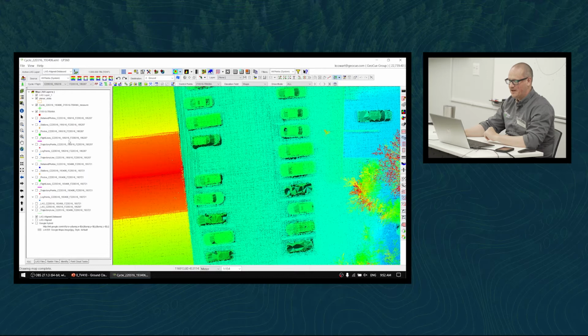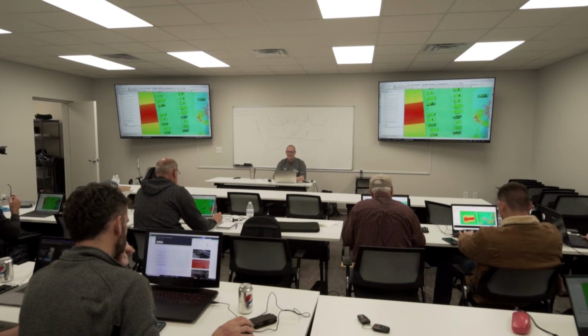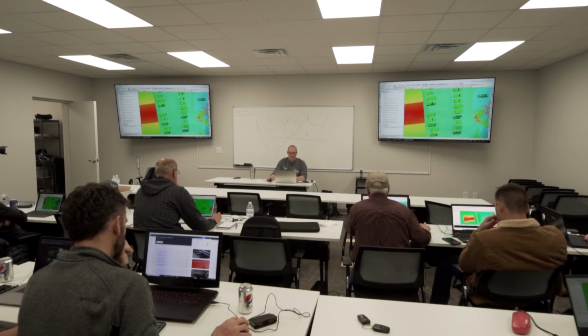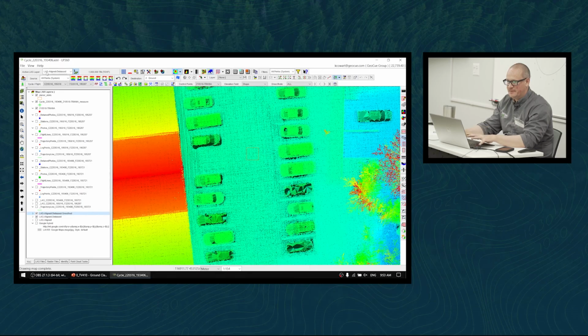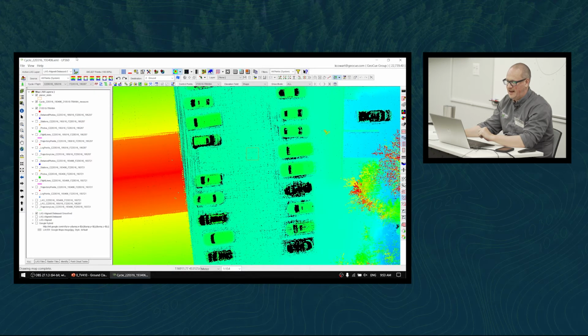Okay, so my smoothing just finished, and I'm sure y'all's is done or about to finish. I'm going to go ahead and go back to my table of contents. And just like last time with the debiasing, I've got just a generic name up here, LAS Layer 1. I'm going to rename mine to LAS-aligned-debiased-smoothed. Again, so that I know not just what steps have been performed to my data, but what order they were performed in as well. And I'm also going to go back to my active LAS layer and change it to that. And because it's a new data set, I'm going to go ahead and hit my 10 view again.